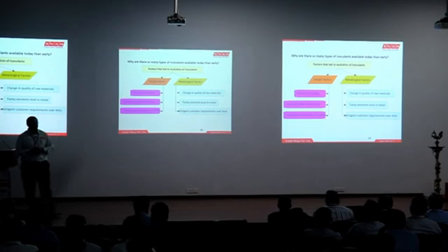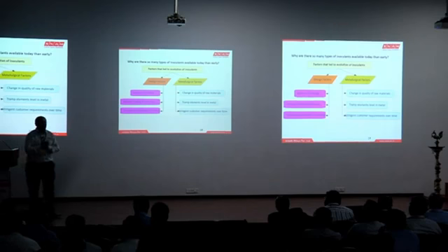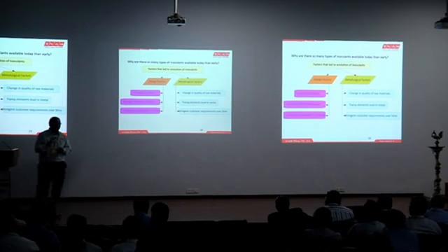But the actual problem is, though you may be able to get the same chemical composition as we have been getting with a different charge mix, when you add different ingredients and make a casting, the property or the functionality of the casting can have a small variation between the one made with one charge mix and the other made with a different charge mix.